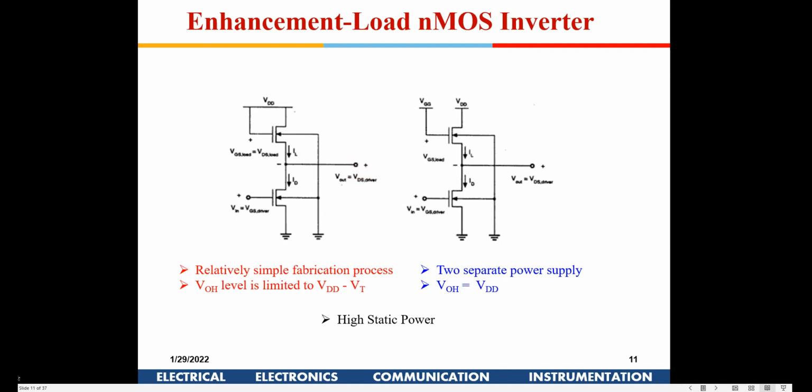Okay, diode connected is like if you have the gate and the drain of an NMOS shorted like this, so it becomes a two terminal device. So it will act like a diode. Now if you see the characteristics here, from 0 up till VT, and this VD is the terminal voltage, right? This can be considered as anode, this can be considered as cathode. Up to VT, this will be off, because VGS is less than VT, and greater than VT, this will be on, and the voltage here will be 0.7 volt.